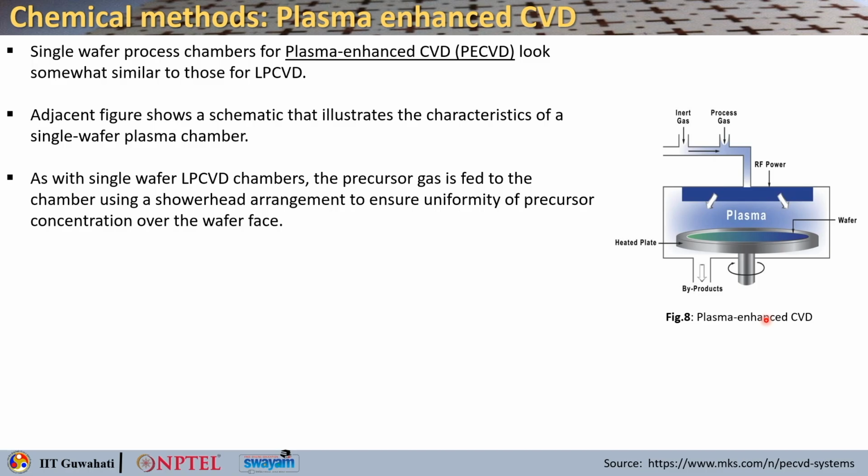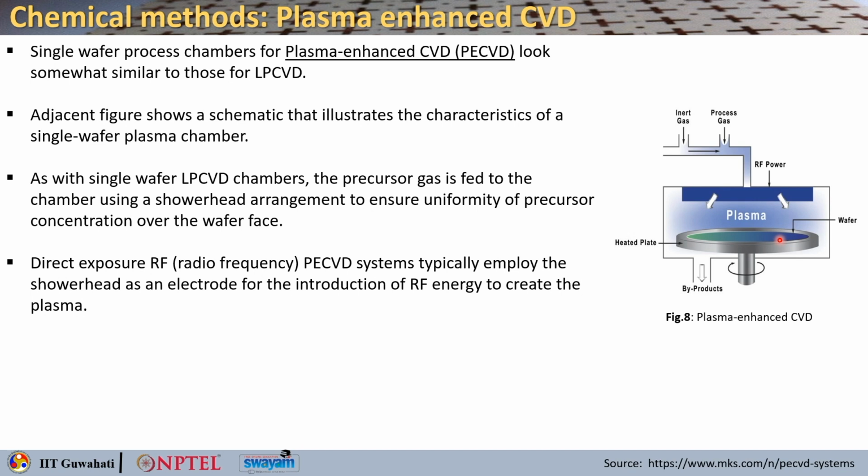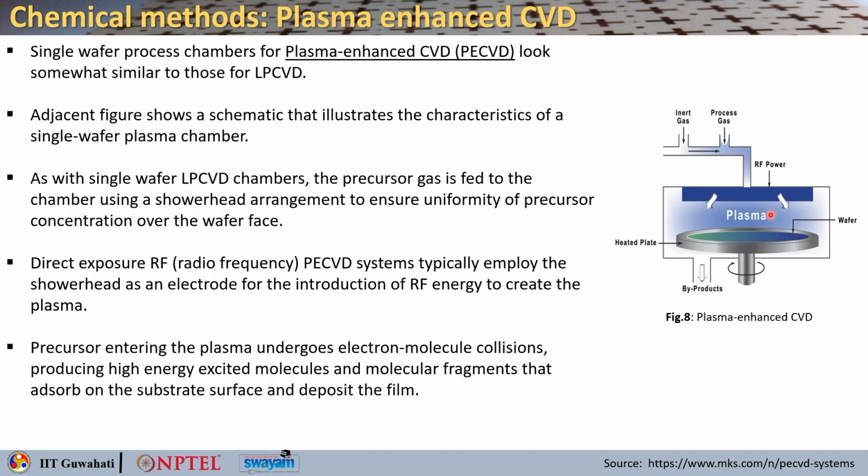As with the single wafer LPCVD chamber, you can see that the precursor gas is fed to the chamber using the shower head arrangement to ensure uniformity of the precursor concentration over the wafer face. This is where the wafer will be lying. Direct exposure radio frequency PECVD systems typically employ the shower head as an electrode for introducing the RF power, or the RF energy, to create the plasma.